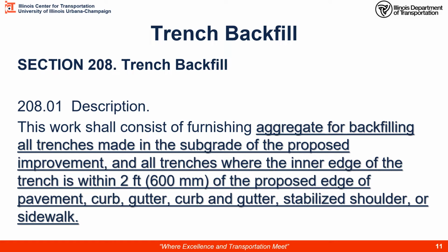So as a result of that, we have a requirement under 20801 that the aggregate for backfilling trenches made in the subgrade of a proposed improvement and all trenches where the inner edge of the trench is within 2 feet. That's the critical dimension here, 2 feet of the proposed edge of pavement, curb and gutter, stabilized shoulder, or sidewalk. So any of these common pavement, sidewalk type elements requires that an aggregate be used for backfilling the trench area.